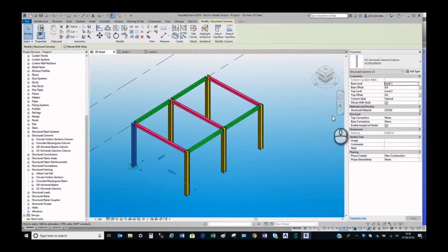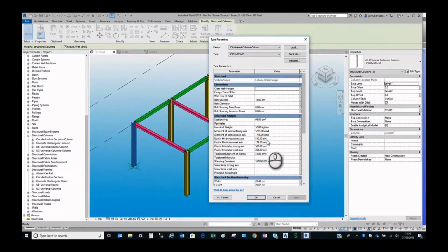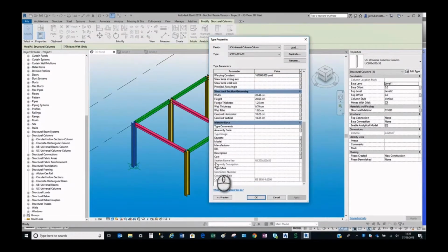But just to come back into the Revit here, you can see I'm navigating the model and looking at the different sections and the properties. I'm just going to show you the section key reference. You can see the section key that I mentioned before. This is an indication that this is an approved family with this trigger, and this triggers the transfer from Revit to Advanced Steel and enables the direct mapping, so you don't really have to worry about anything. From my experience, I found this mechanism does work very well.